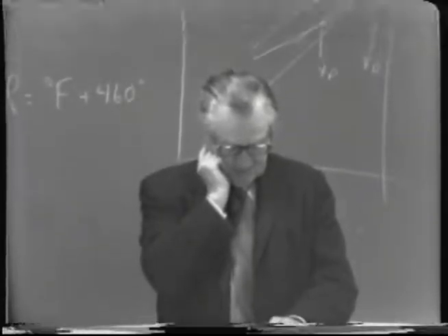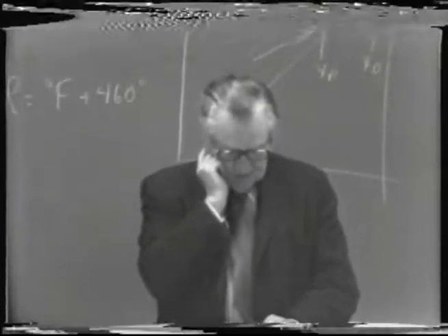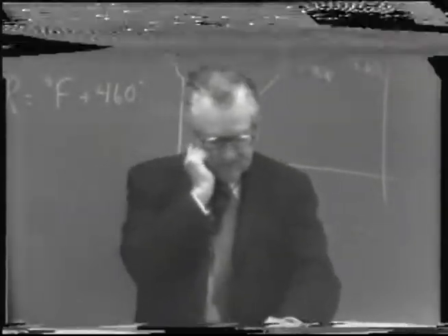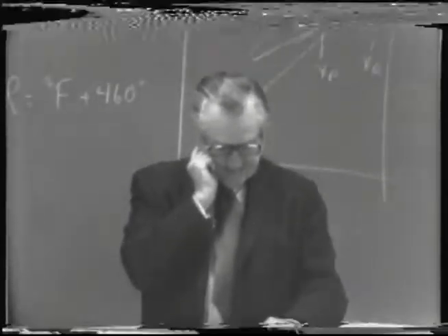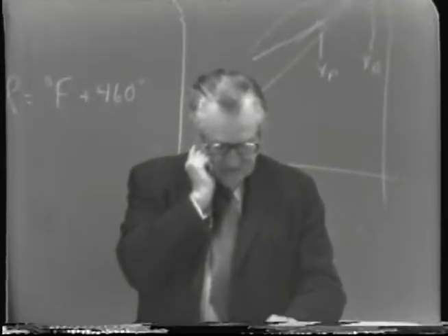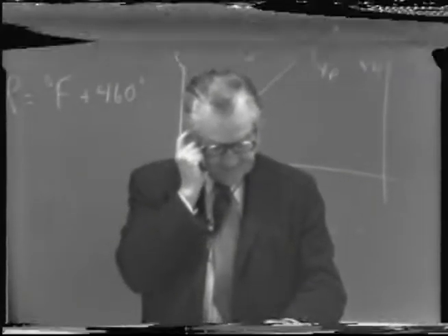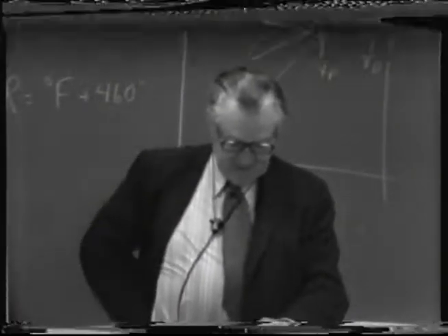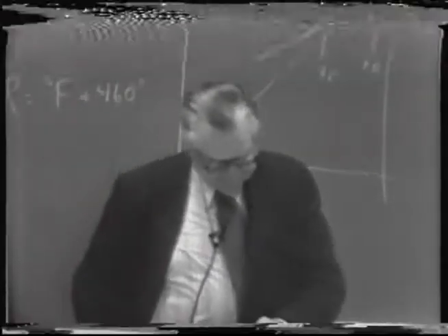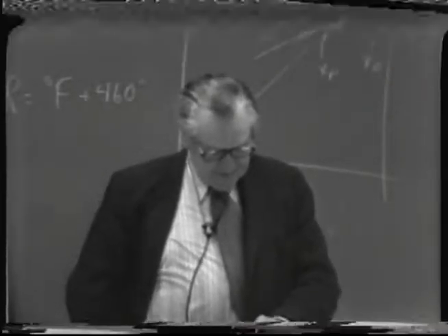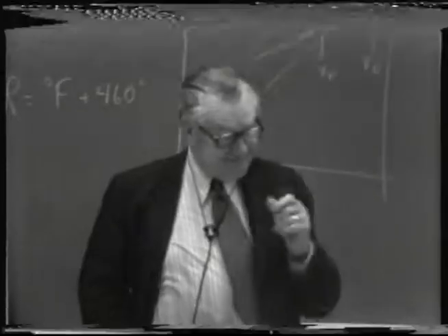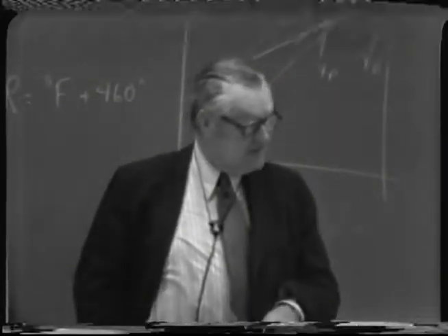And so, substituting those values in here, we'll see that we have to add to 928, the vapor rate in the top part of the column, the rectifying section, the additional value of 468 moles of vapor. In other words, about 50% as much vapor was condensed at the feed tray as passes on up. 468 versus 928.